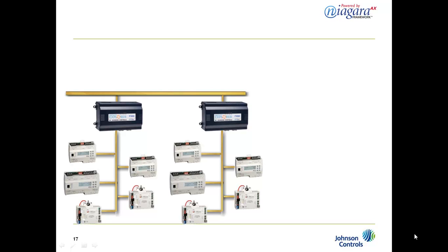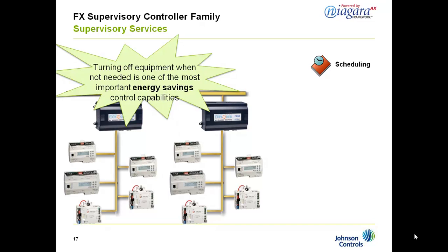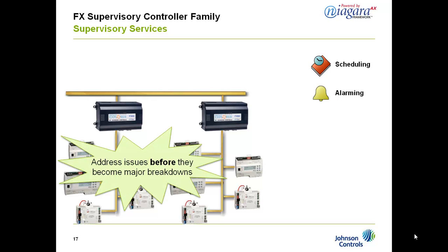Once the field devices have been integrated into the FX Supervisory controller's station database, a wide assortment of supervisory services are available to be applied to those devices to provide system-wide coordinated control. Some examples of these supervisory services are scheduling, to automatically turn equipment on only when it's really needed and off when it's not. Alarming, to identify those data points which are out of range or are not normal, and to alert operators of issues before they become major breakdowns.